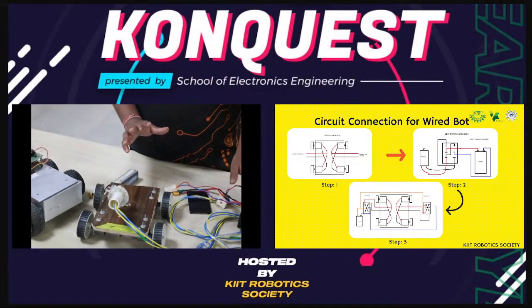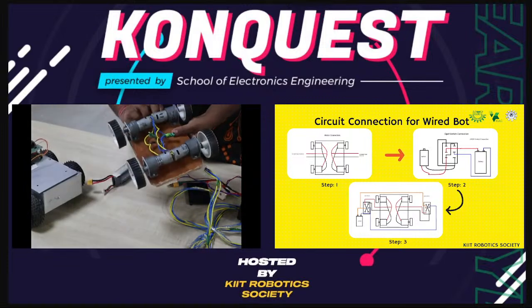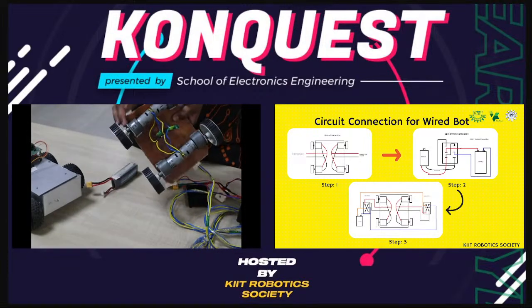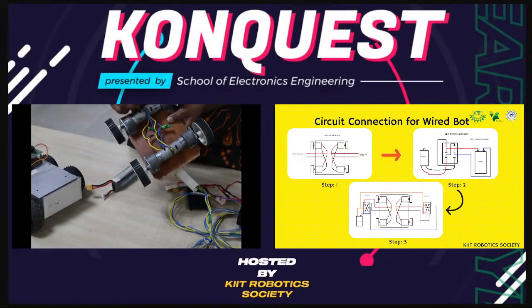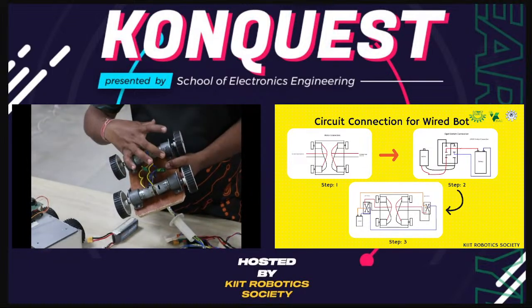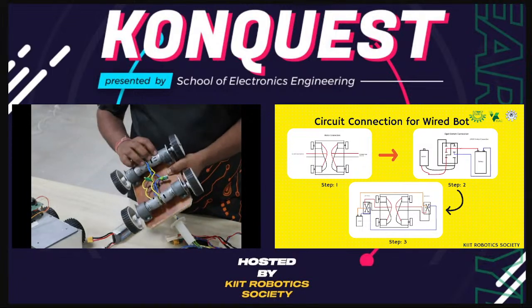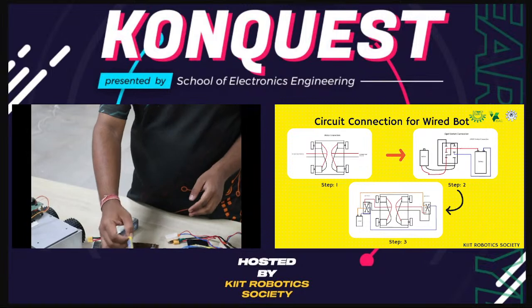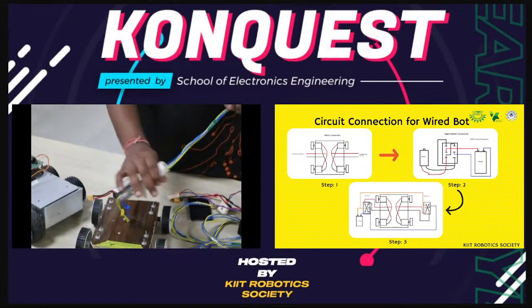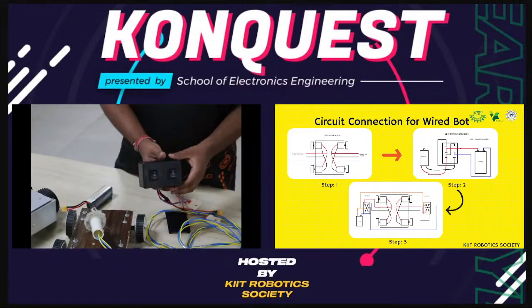For the wired bot, you just need this connection only. You just have to put the L clamps on the motors, connect the common ground, common positive voltage, common negative of the right side motor. Same goes for the left side motor, and take out that common wire from here. Now, this was the controller that we have designed for our wired bot.